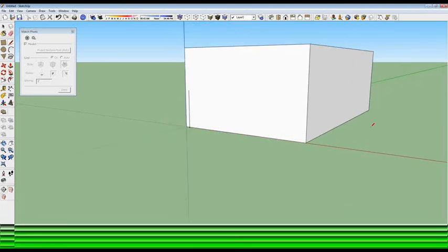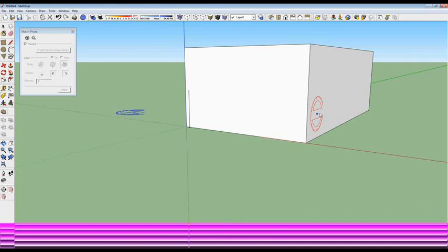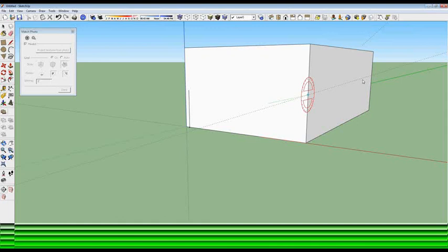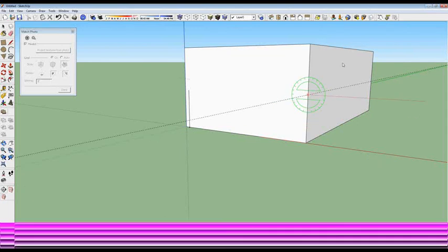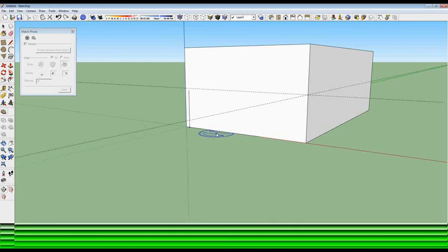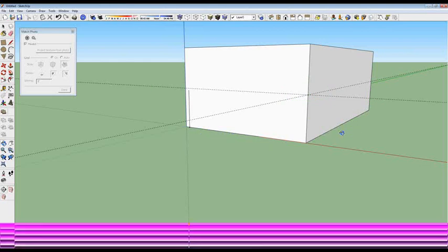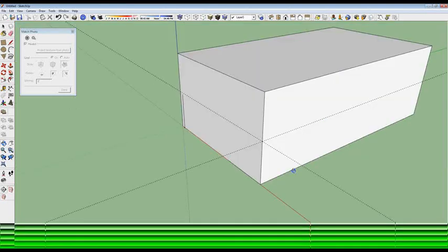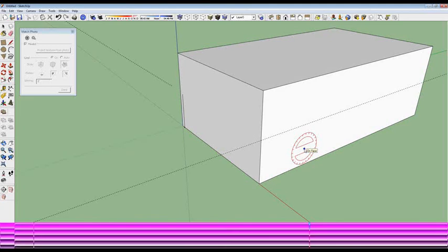And another one actually is this protractor, which is excellent for getting things in the exact proper location and making sure everything is lined up. The protractor itself, you'd simply attach it to the face, and you'd give it essentially a directional orientation, and then you can put in what are just guidelines. So I'd be able to use that same point, make sure my directional face is in here, and I would be able to make sure on my building that everything is lined up as need be. And again, you can do these at specific sizes.